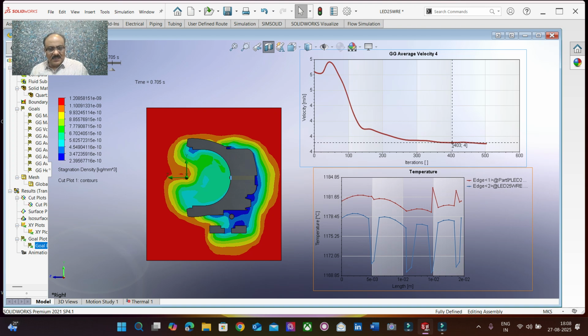The reason is that there is a convection induced and the air suddenly cools down that particular part of the system, and that's the reason the temperature is dropping, and then again it is trying to increase. At various stages of the calculations, the solver is trying to converge, but there are still some parameters inducing a shift in the convergence rate, and then again it comes down. That's the reason we find this particular staggeredness.